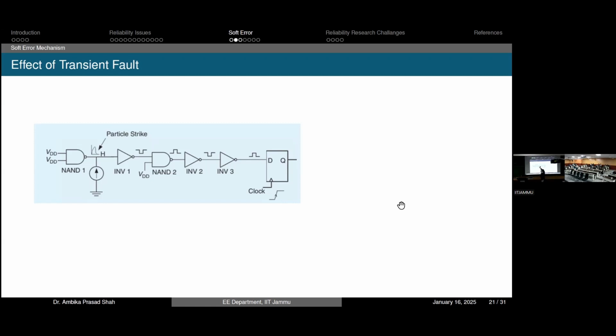So let us assume, leave these two things. I will tell you later on what is the importance of these two. Let us assume I have this inverter, and again I have passed through one more inverter. So what will I get? I will get a pulse something like this one. This will be a complemented version of this pulse. Now, in reality, let us assume here is logic 1. After passing through the inverter, it should be logic 0. Here I'm expecting logic 1. And again, if I'm passing it through one more inverter, the logic will be 0.